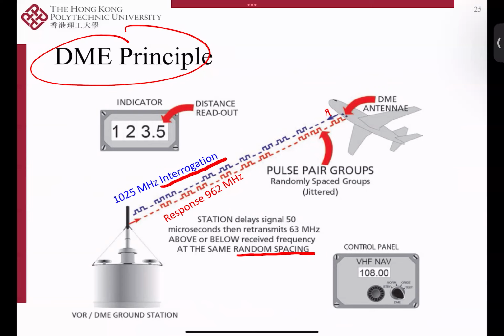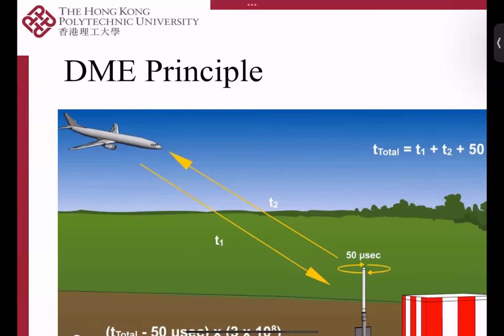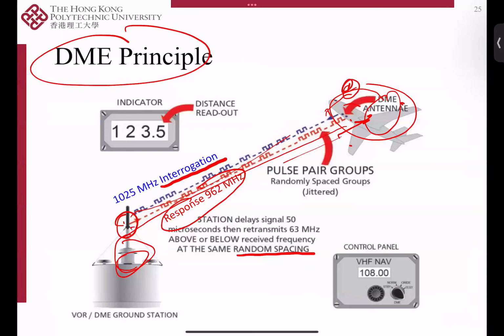It actually emits from our aircraft and goes to our station, where it is not reflected but processed a bit, and then sent with another frequency back to our aircraft, so that the information is displayed on the indicator on our aircraft and seen by our pilot.